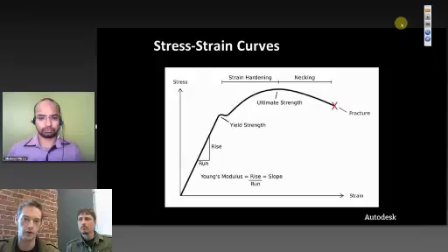You generally are not going to want things to permanently deform. There are notable examples where you would, such as in a car frame, you want the frame of the car to yield, to take up a lot of that energy of an impact. But in most situations, you want to make sure that when you get off your chair, it's in the original shape it was in. It didn't bend permanently from you sitting on it. So you're going to want to usually use yield strength as the maximum criterion for safety factors, which we're going to talk about next. So safety factor is really important.